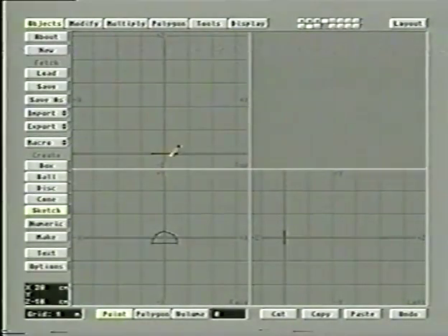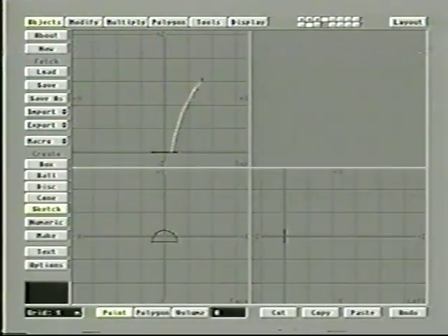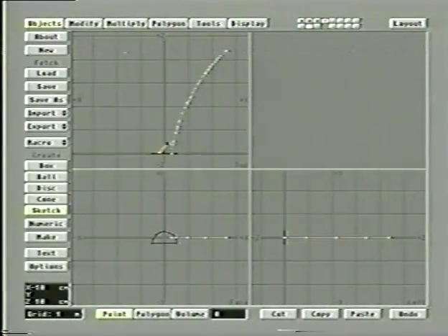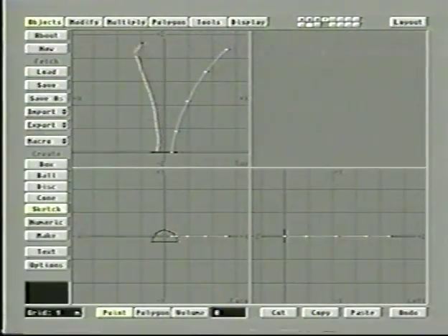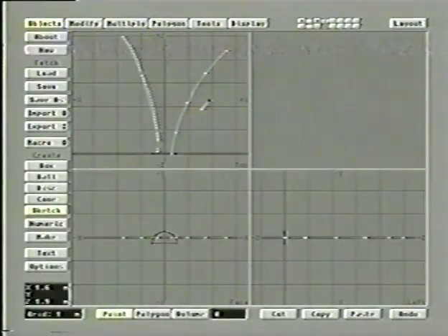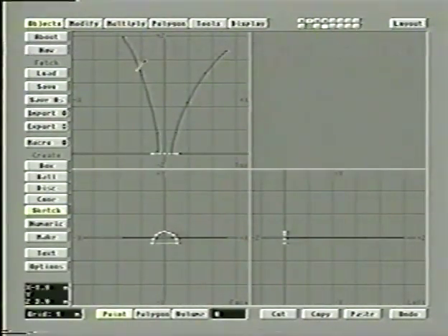Now, if we were to create, instead of one sketch path in the background layer, 2 sketch paths, you end up with what's called multiple rail extrude. And let me just redraw our sketch paths here to give you another example of the way you'd use that. Using sketch. One up this way. We'll make that one. Then one up this way. We'll make that. Now again, we use the quote key to flip our layers. So the rails are in the background layer, the object's in the foreground.